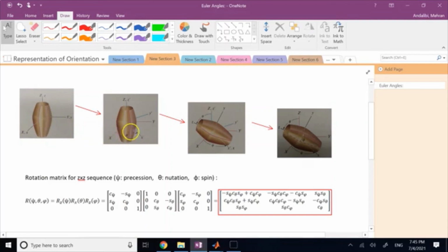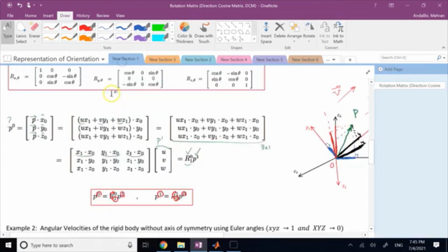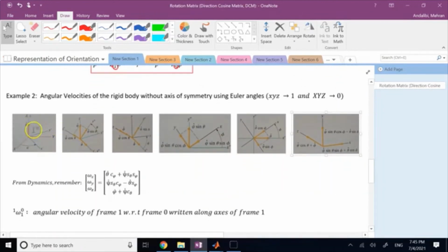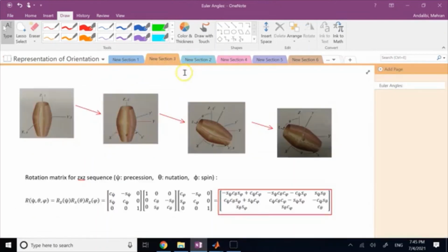First, you rotate about the z-axis by angle psi, and the resulting angular velocity of that, you call it psi dot. So psi dot is about the cap Z or the initial z. Then, whenever you get the first intermediate frame, you call it x prime, y prime, z prime.